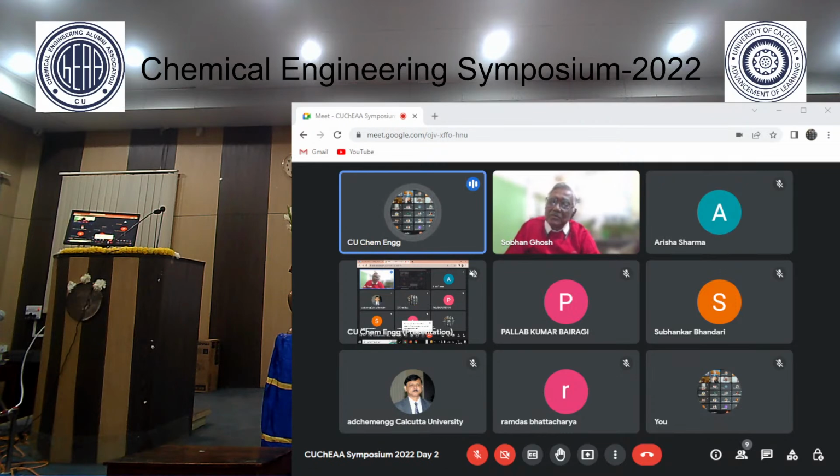Hello. The question is, have you compared the steam to carbon ratio with your results as well? As what Somonda asked about the nitrogen, you will have NOx formation in your product, because you cannot control NOx formation if you have nitrogen and the temperature.